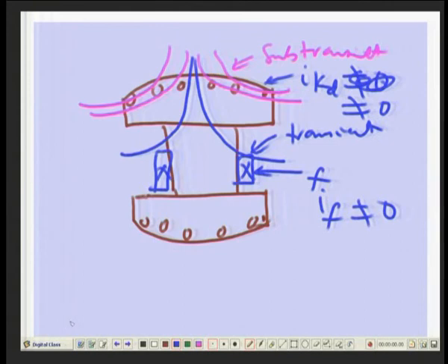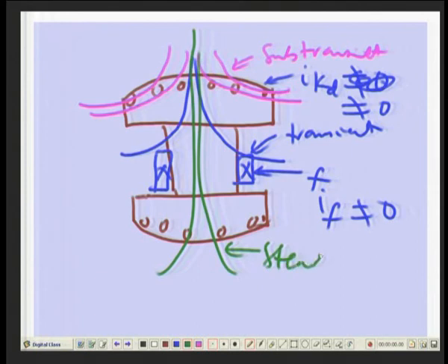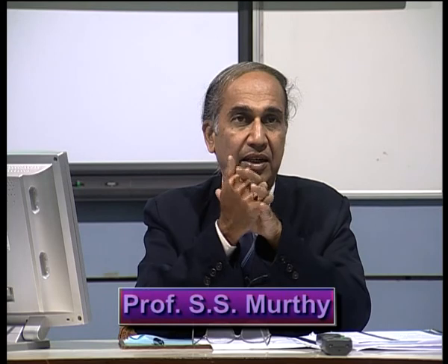Okay. Then afterwards when it comes to steady state the whole flux will penetrate. When the steady state, what will happen, the transient field current or transient damper currents will be 0, right. So, this is a physical interpretation of the short circuit conditions.